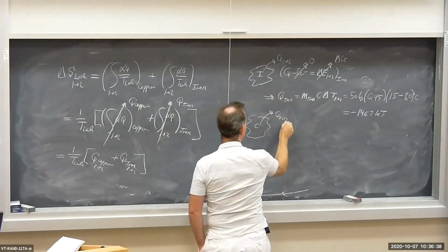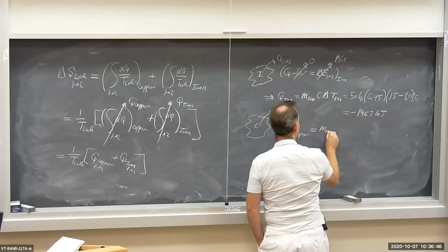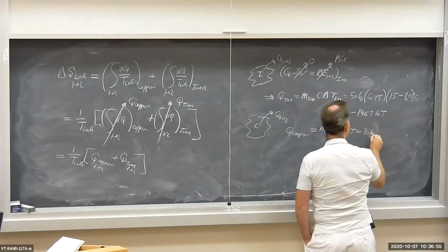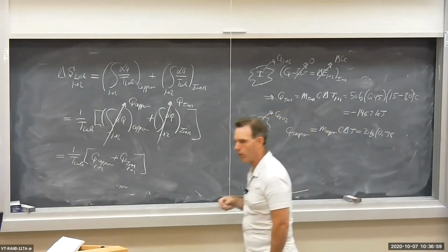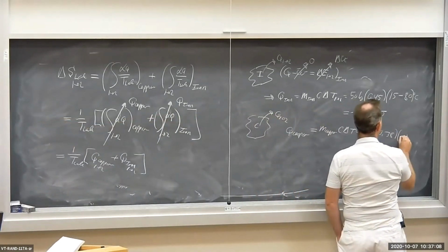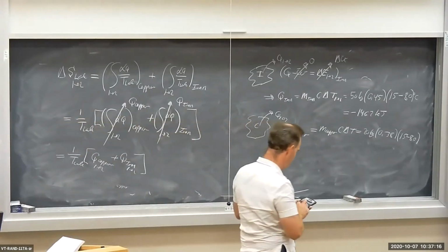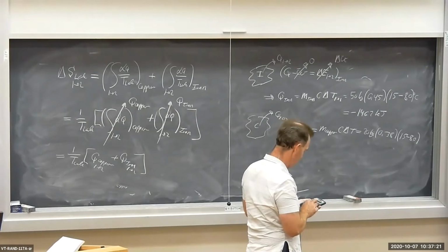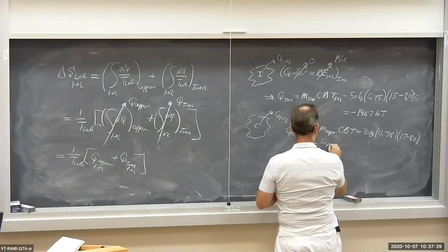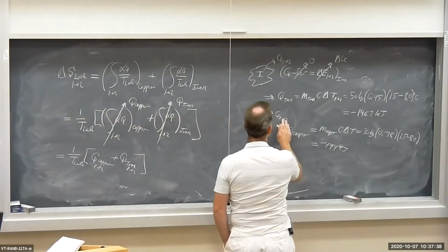What's the heat being rejected from the copper? Well, that's going to be Q copper equals M copper, C for the copper, delta T. So what do we have? 20 kilograms, 0.38 as I recall. Is that what I put down? 0.38. Yes, 0.38. And then we have 15 minus 80. So we have 20 times 0.38 times 15 minus 80. Negative 494 kilojoules, okay? So that's heat being rejected from the copper from state 1 to state 2.